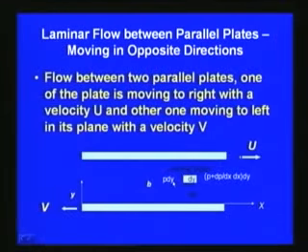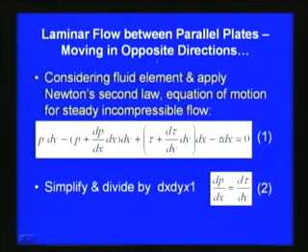Here also, as in the previous case, the forces are the pressure force p dy on the left hand side and p plus dp by dx into dx into dy on the other side, and then we have the shear stress. Here it is tau dx on the bottom, and on the top of the fluid element it is tau plus d tau by dy into dx. So, the principle is essentially the same. We are considering the problem in a very similar way.